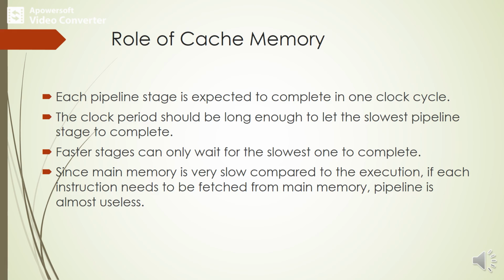Each stage in a pipeline is expected to complete its operation in one cycle. Hence, the clock period should be sufficiently long to complete the task being performed in any stage. If different units require different amounts of time, the clock period must allow the longest task to be completed. Suppose you have a set of operations that can take different numbers of clock cycles, meaning some operations take longer to complete.